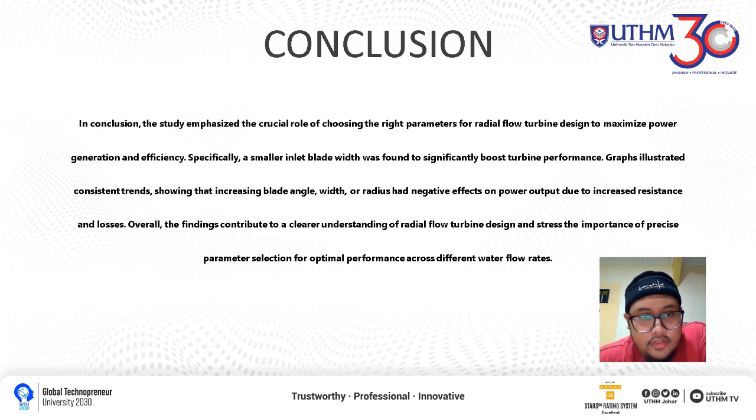The graphs illustrate a consistent trend showing that increasing blade angle, width or radius had a negative effect on power output due to increased resistance and losses. Overall, the findings contribute to a clearer understanding of radial flow turbine design and stress the importance of precise parameter selection for optimal performance across different water flow rates.